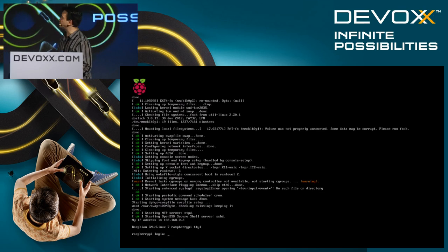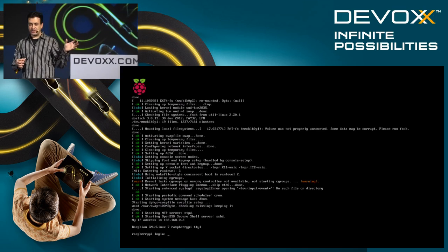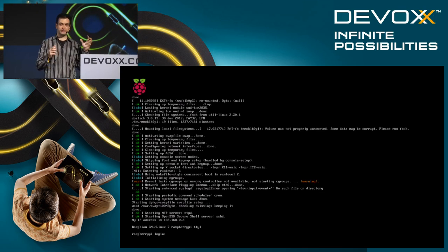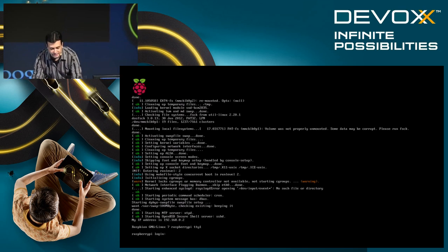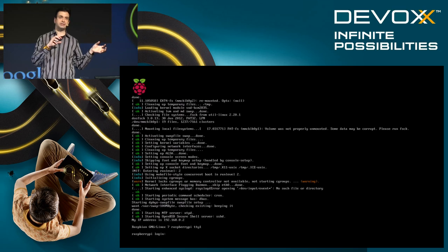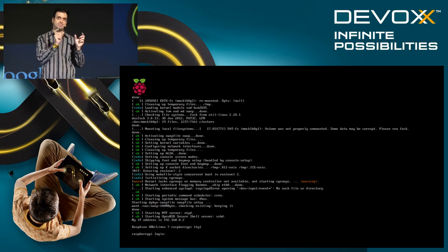So there was a question about how the similarities on the inputs and outputs relate to ladder logic, right? I'll do my best to answer that. I'm not sure how effectively I can answer that question, but certainly with all of the different inputs, if you want to tie inputs to outputs or do very concrete actions, there are other functions in Pi4J that can provide that functionality. We didn't talk about triggers today, but there's a concept of triggers where you can intimately tie an input and an output together. Either they can be in a synchronized state or in an inverse state so that they're in direct opposite, or you can simply invoke a triggered behavior on the output through the input, without having to write a bunch of code. It's more like a binding expression, if you will, where you can bind this behavior to the input state change. Does that kind of get close to what you're asking?